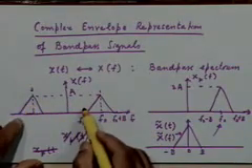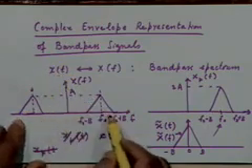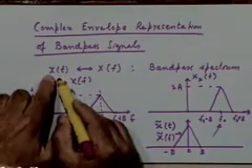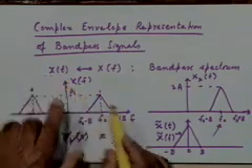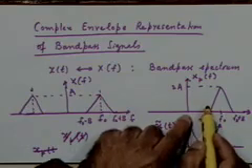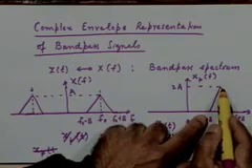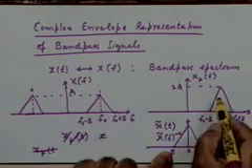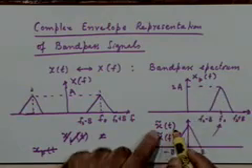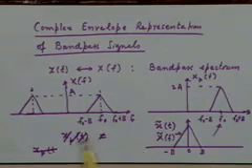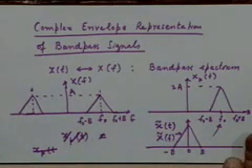Our whole discussion on this point started with x(t) having this band pass spectrum. So our x(t) is band pass. We represented x(t) as the real part of x_p(t), which is still band pass. We represented x_p(t) in terms of x tilde t, which is low pass. X tilde t being low pass means x_R(t) and x_I(t) are both low pass signals.